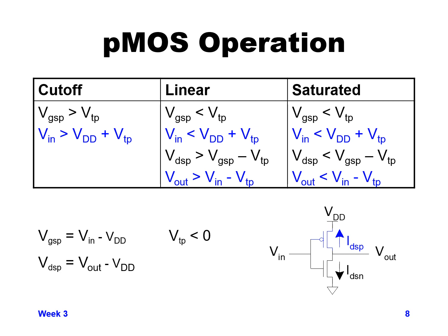And then for saturation region, you're in saturation if Vn is less than VDD plus VTP and Vout is less than Vn minus VTP. So those are the equations. Just keep in mind that in order to be in saturation region, your Vn has to be low enough to turn the transistor on, and Vout has to be lower than Vn by enough value to go into saturation.